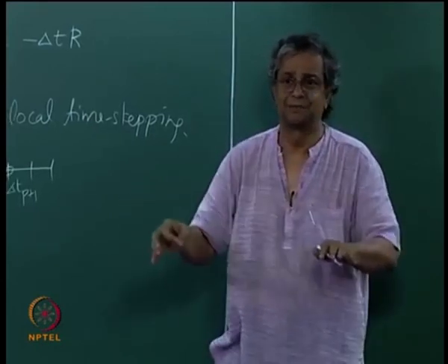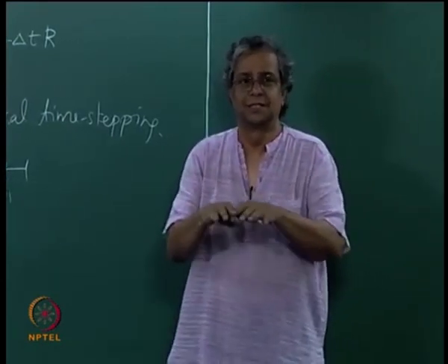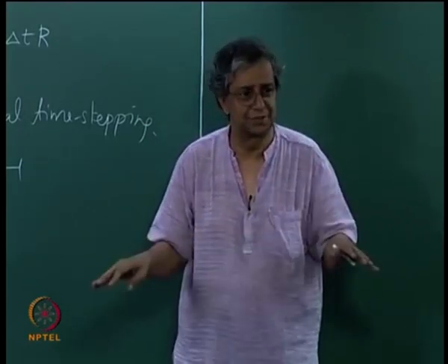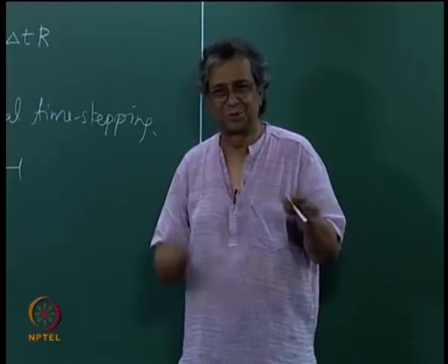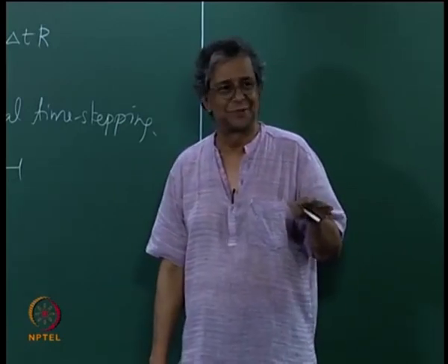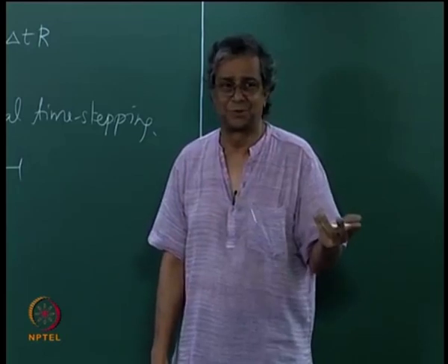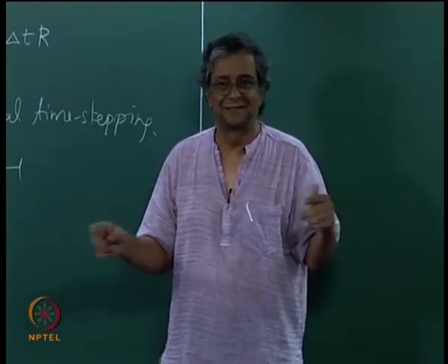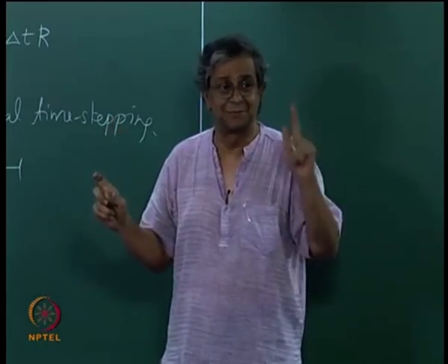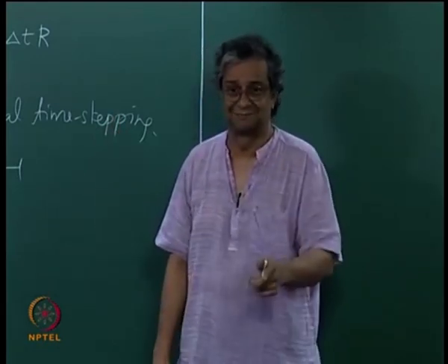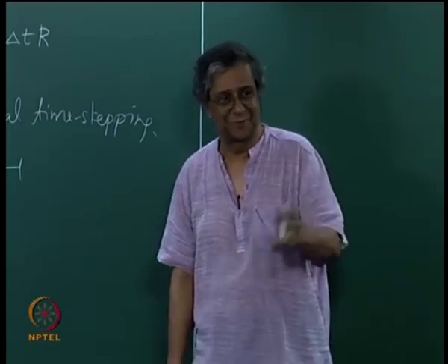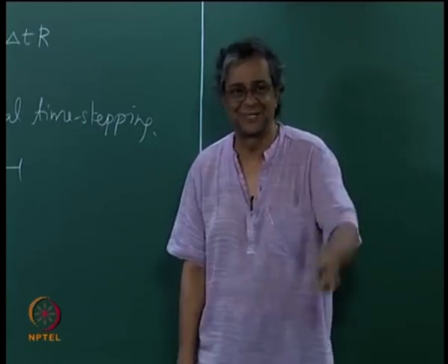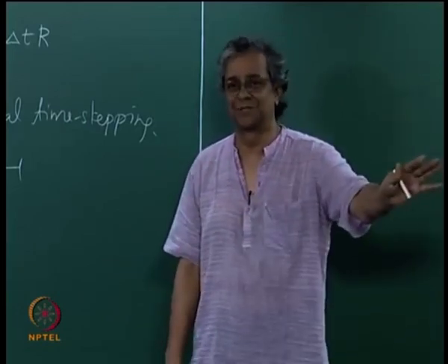to point in the domain, my solution is... so it is no longer, if I say solution at first time step, solution at second time step, solution at third time step, they are not really a solution. I can't even imagine it as a candidate solution. It's basically some state vector q at the first time step, whatever that means, right? But I say first time step, I don't say at delta t. My language has already changed. It's not at delta t, 2 delta t, 3 delta t, because I am not bothered about the transient.